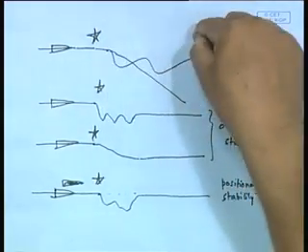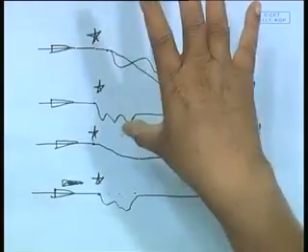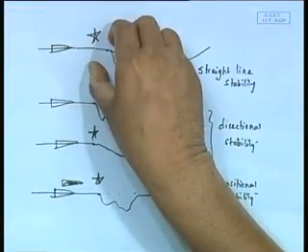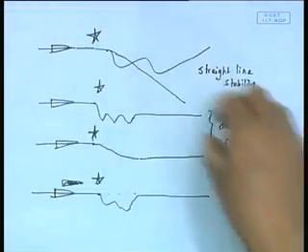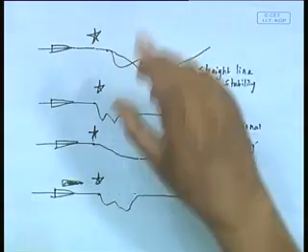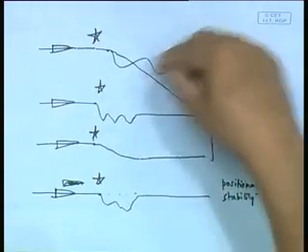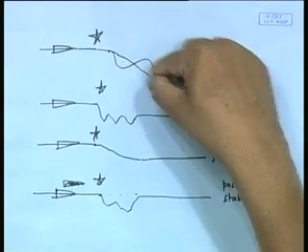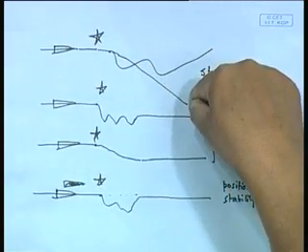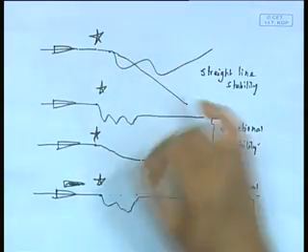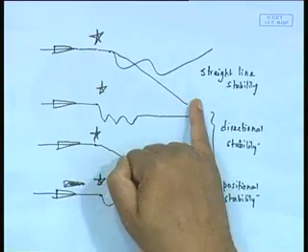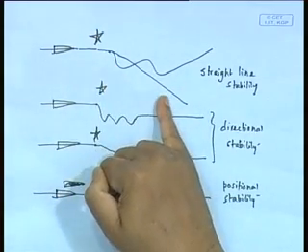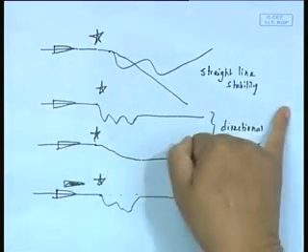Now what happened? The ship, there can be 2 possibilities, the ship can go along a straight line, but it will not be the same straight line, because there is nothing to restore it back. Remember, because it has got some change of heading, you have a propeller thrust, so it cannot come back to its line. But that is one, but it may also completely go in a haywire manner. So if it goes in this line, if it possesses a characteristic of following another straight line after disturbance, we call that the particular vessel possesses straight line stability.